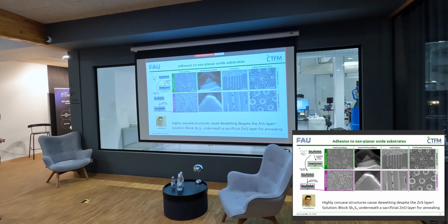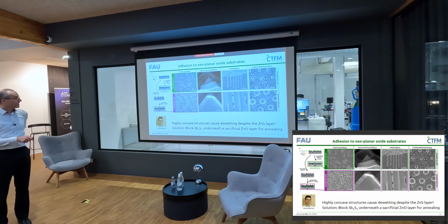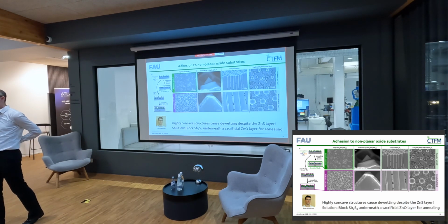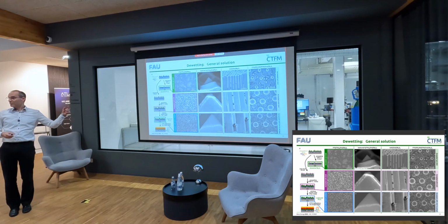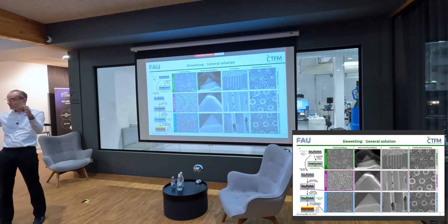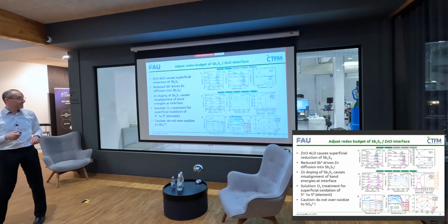However, upon annealing, just to be clear, if on top we deposit titanium oxide, then zinc sulfide, then antimony sulfide, and then zinc oxide and anneal, the zinc oxide layer basically blocks everything and holds it in place. The antimony sulfide cannot move, so that after that, you can remove the zinc oxide and get to the desired crystalline but smooth, conformal, continuous antimony sulfide layer.